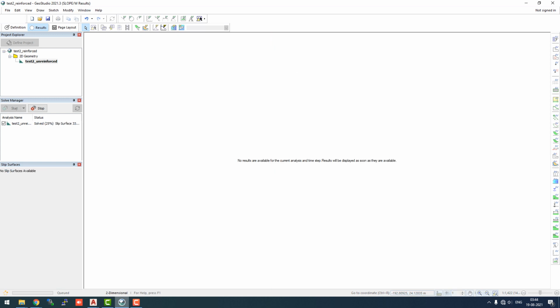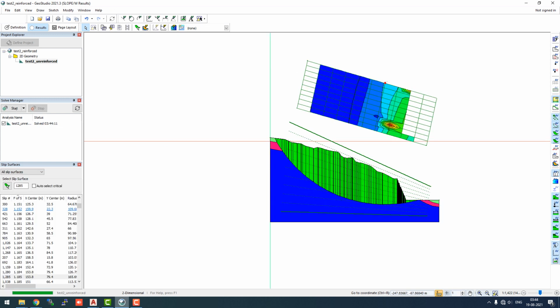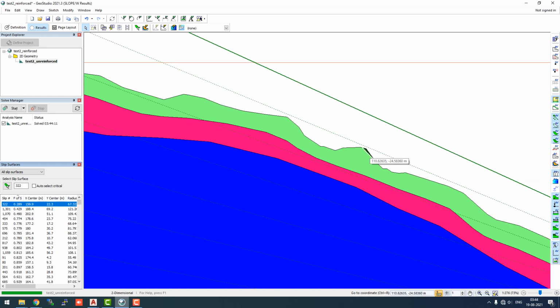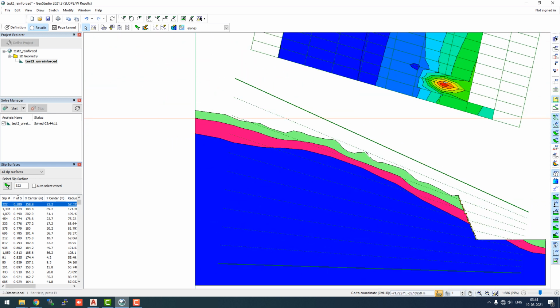So I guess the wait is already over. Now you can see that the factor of safety has been increased in several cases. The smaller failures are actually inevitable. The smaller failures at the top are occurring anyway, because the RCC cladding wall does not cover that top part.